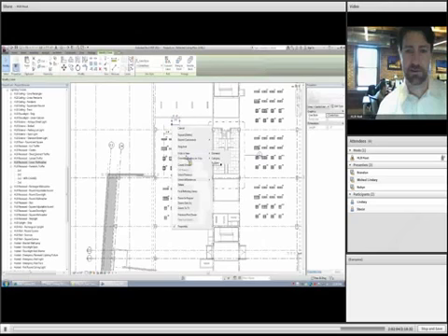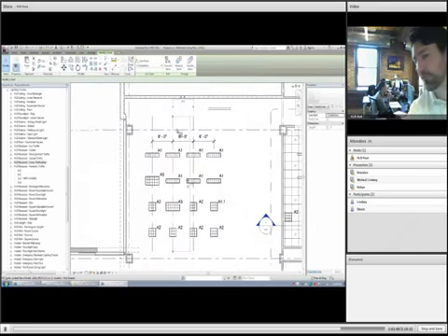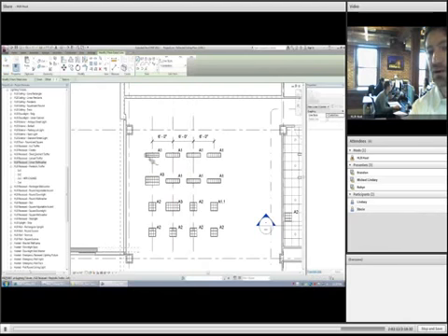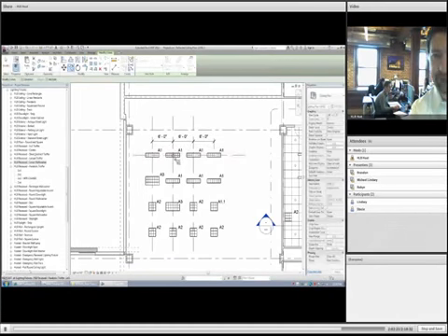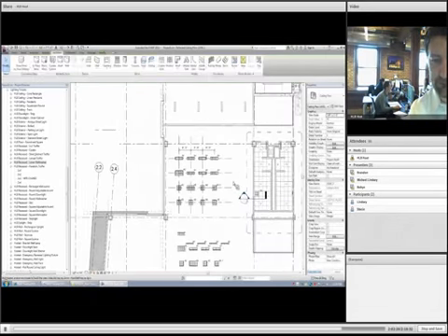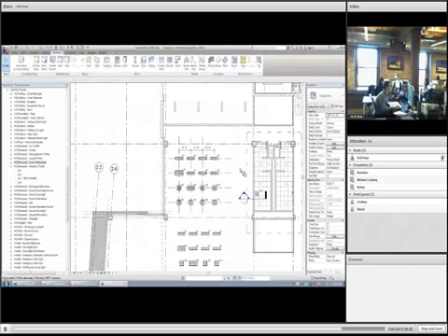Okay, so a lot of times I use these detail lines, and if you remember one thing in the drawing area that you like and you like the way it looks, you can right-click and do a create similar. We can copy multiple. There you go, if you want to do a quick layout grid. You could even align your light fixtures to this detail line grid once you get it just the way you like it.